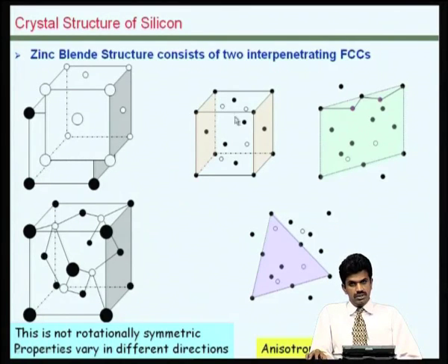Hence, the structure of the silicon is not rotationally isotropic and the properties are different. And as you have seen here, once you hit this 111 plane, all the atoms are bonded very strongly to those below them and hence are difficult to be displaced. Hence, we get a smooth continuous plane if the etch window is aligned properly.